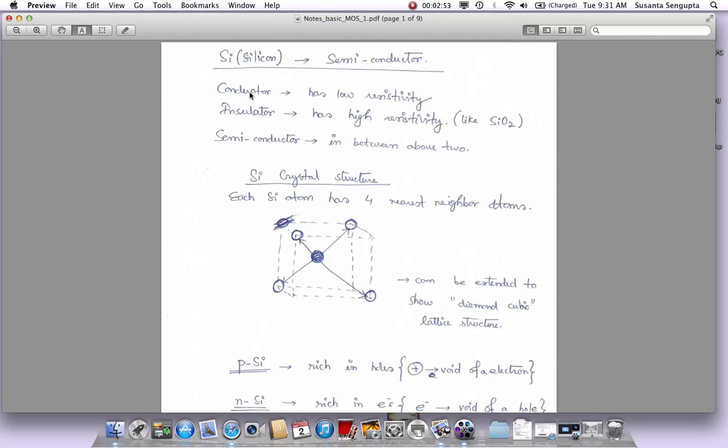It's called a semiconductor because it falls in between the two. It's not a very good conductor, it's also not an insulator, and that's where we use it. One of the other reasons we use it is that, since it's in between the two, you could actually change its property, and that is the main property that's been exploited, to turn it on heavily to act like a conductor, or turn it off so it acts like an insulator. So a semiconductor is in between the two, and it is programmable, and we'll see how you could make it act like a conductor or like an insulator.